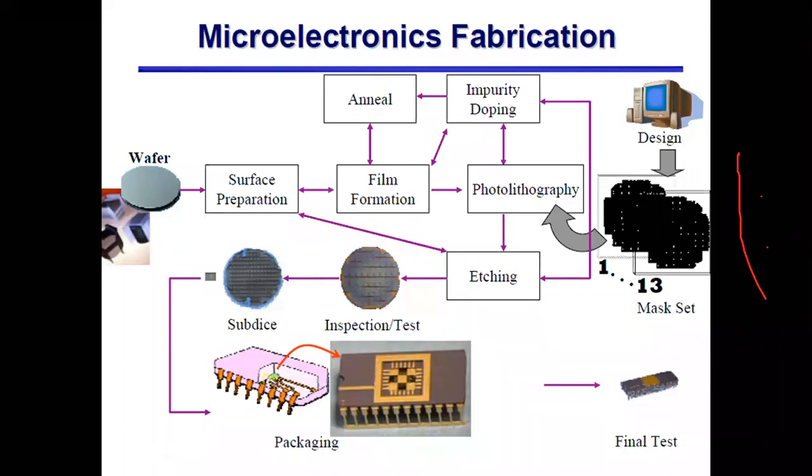So you have to look at the recipe by which you clean the silicon wafer. First you wash your silicon wafer with isopropanol, then you rinse with DI water, and then you dry with nitrogen gas.